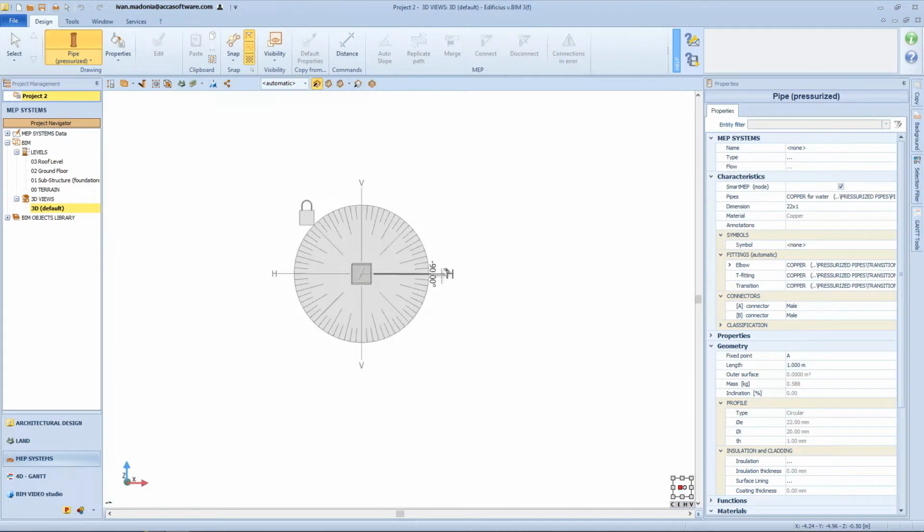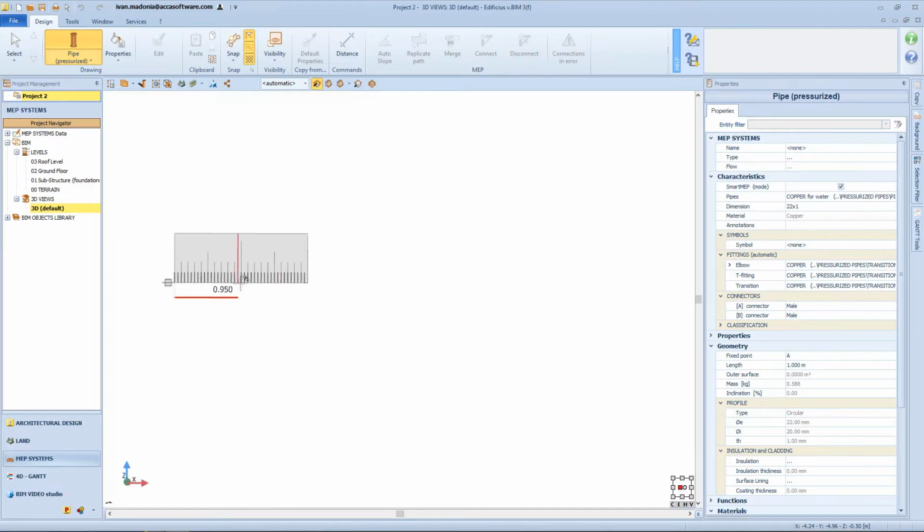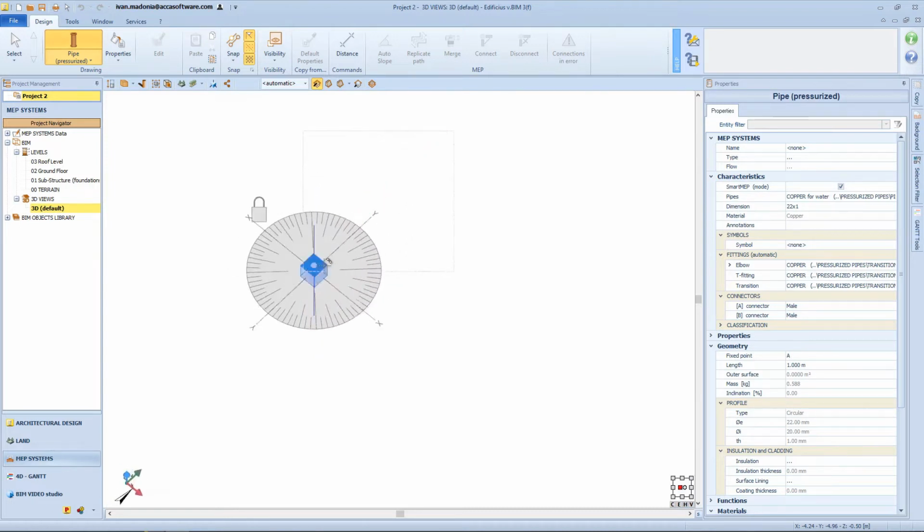Once the angle has been identified, a click of the mouse is enough to fix the pipe along the direction and according to the chosen verse. A ruler appears on the screen that can be used to define the pipe length in the next step. If you realize that the chosen angle is wrong for some reason, go back to the previous step by clicking on the cube on the starting point of the ruler. In this way you can choose another direction or another plane.